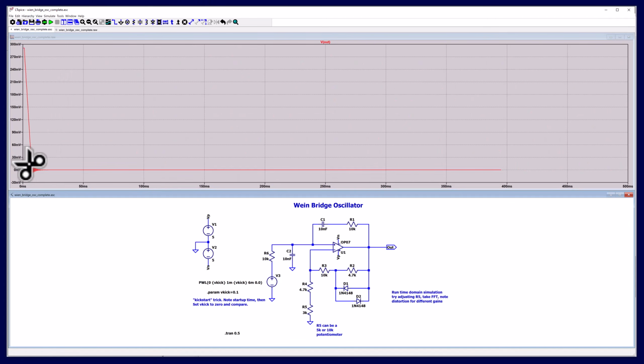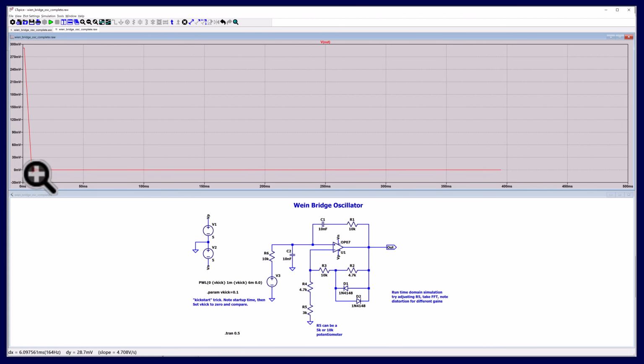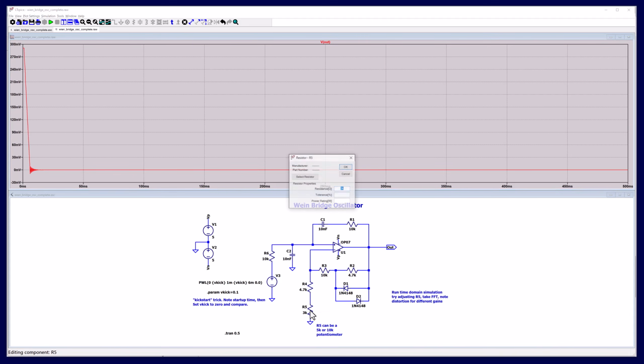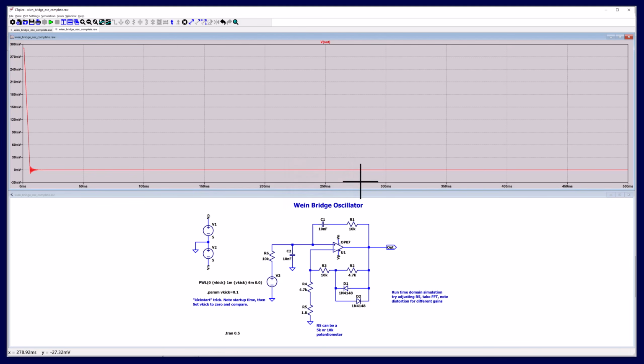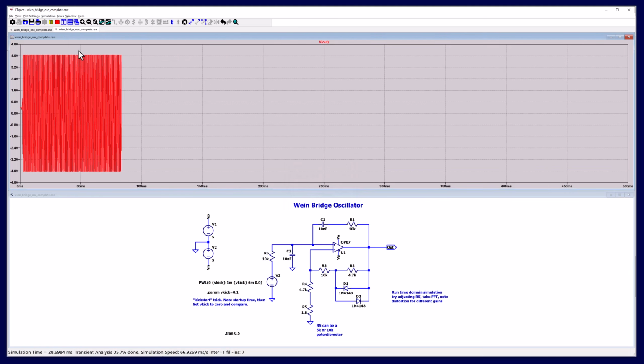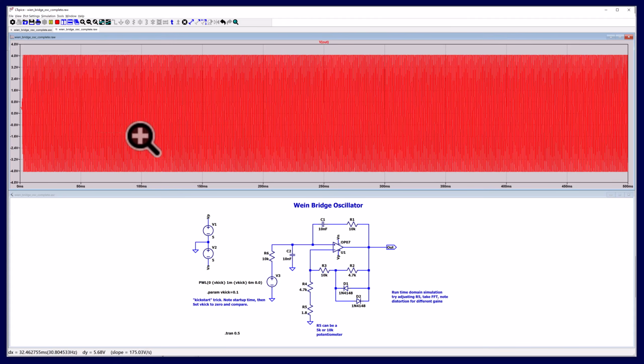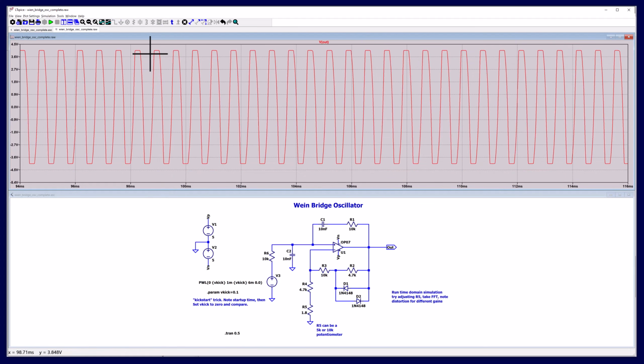And look at that. Just like before, I get an initial oscillation, but then it very quickly dies out. Okay, so let's interpolate and see if we can find just about right. So 2K, I know, let's try 1.8K. Okay, I know that is, yeah, so that's going to oscillate. Okay, and then let's see, any visual? Yeah, so here again, I've got visual clipping here.